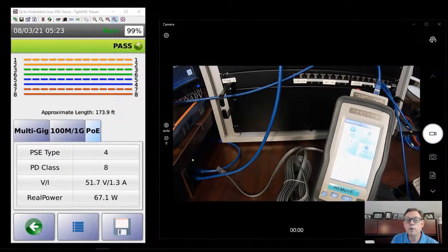Issues with the cabling itself during manufacture or installation can also cause resistance issues. A good example is excess pulling tension. If you pull a cable too hard, you can change the geometry of the cable and alter that copper conductor to the point where the resistance value will change, and it might change on one pair and not another. So any number of things could impact that.